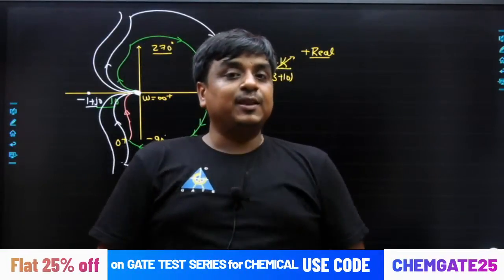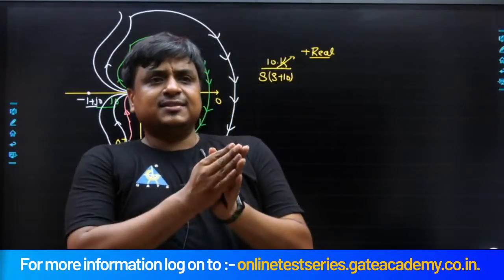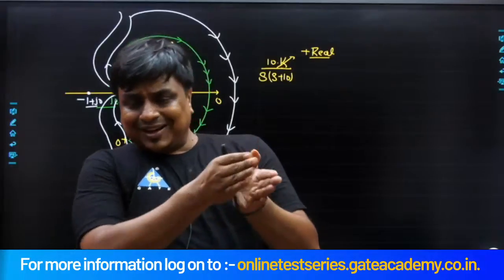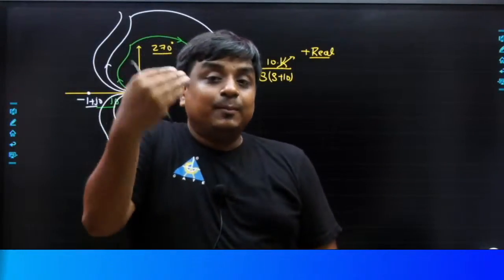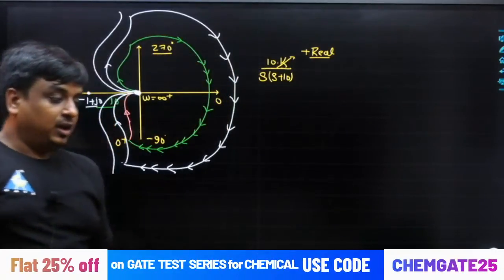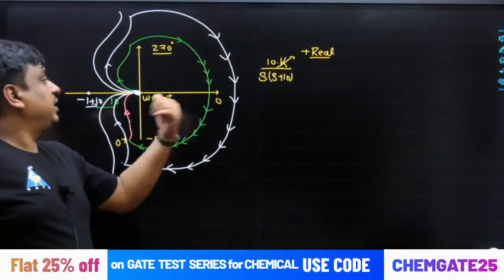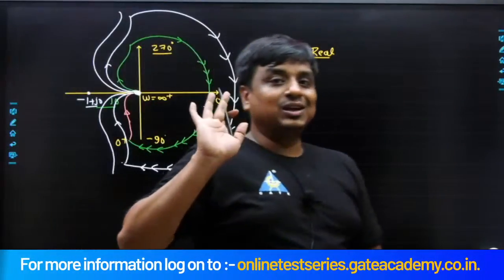Just feel like the gain margin is the margin in gain, how much gain we can pump into the system such that the system is a stable system but reaches the verge of instability. That means if you provide gain more than that value, the system would become an unstable system. But here, there is not any chance at all. Could you really understand what I am saying?